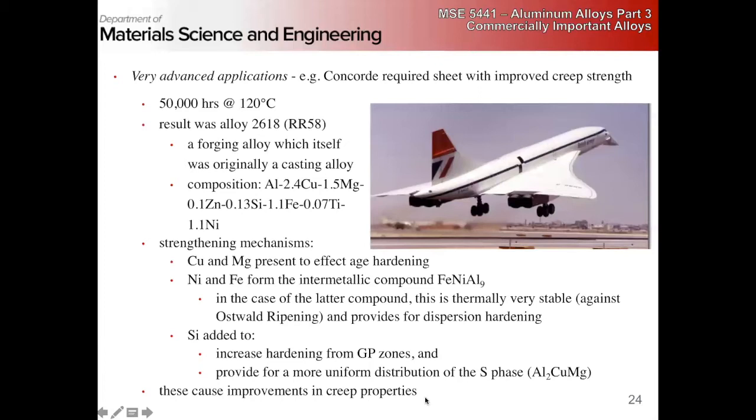And in general, this is sort of representative of the strategies for modern alloy design. We're not thinking about one effect, copper magnesium precipitation hardening, GP zones, intermediate phase, second intermediate phase, thermodynamically stable phase. We're doing multiple things at once. So we have different families of precipitates that are doing different duties.